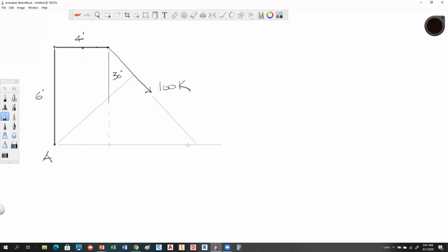I can solve this distance. My drawing is not to scale, just recognize that. And also recognize that this is a 90-degree angle here, because I have to know this distance. So I don't know this distance. If I want to solve this moment with this force about that point, I have to know the perpendicular distance. Does everybody see what I'm getting at? Yes?